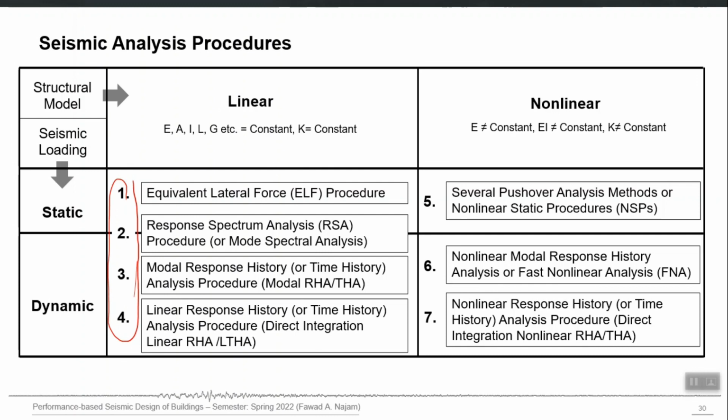But now we provided less capacity and we make it very ductile. So now it will go in nonlinear range when the real earthquake hits, but that real earthquake will not be able to produce 800 kilonewton now, right, because the path which our structure will follow will not be linear now.